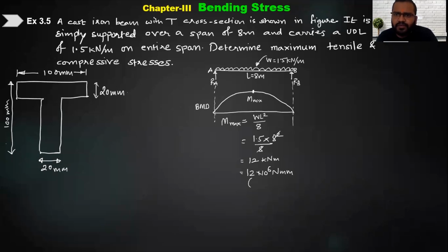Those who are typing in the chat box, I'll request them to come up and speak, because I will know who is speaking. Okay, so let's continue. Sagging is correct because the beam is simply supported, and if I'm giving the load from here, it is going to bend in the downward direction. So it forms a bowl shape, that is sagging. If it forms an upside-down bowl, in common language we call it hogging. So sagging means this way, and hogging is the upside-down bowl.